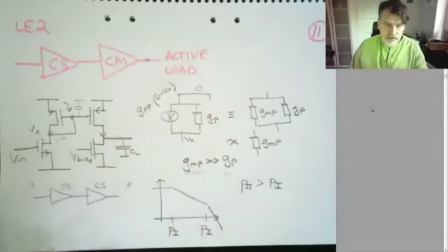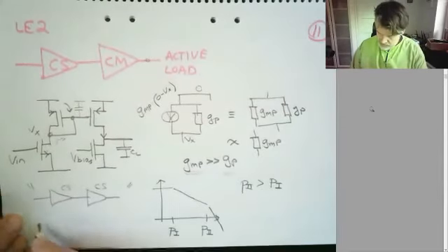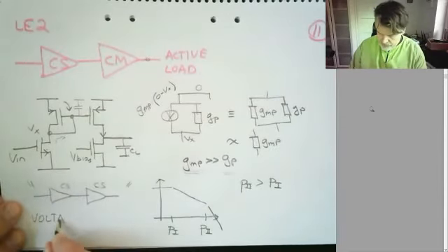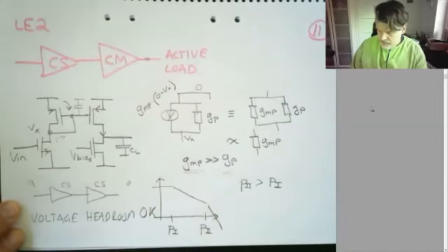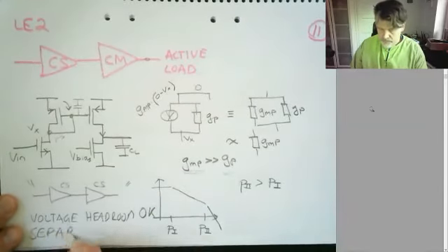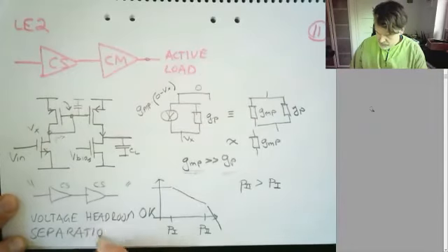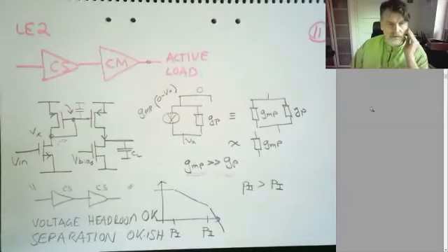And voltage headroom is fine. We only stack 2 transistors on top of each other, so voltage headroom is okay. And separation of poles is okay-ish in comparison.